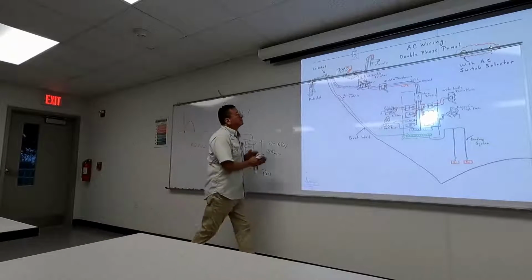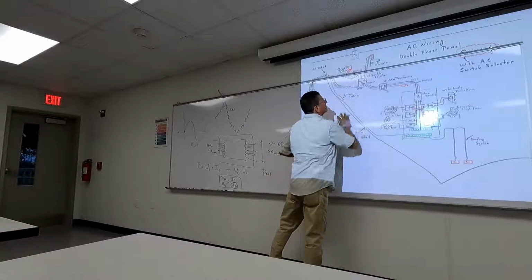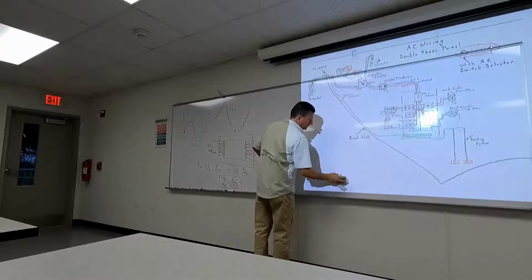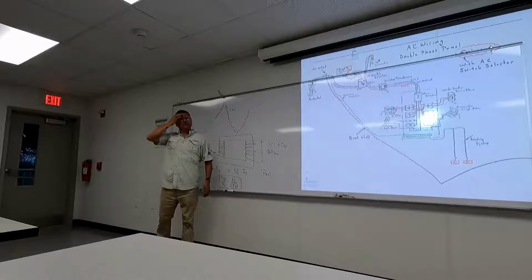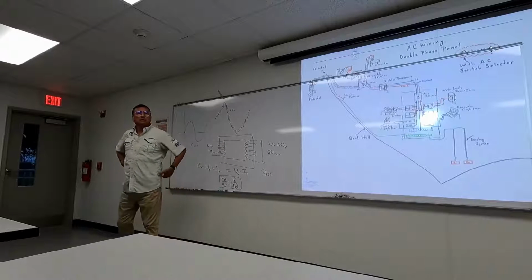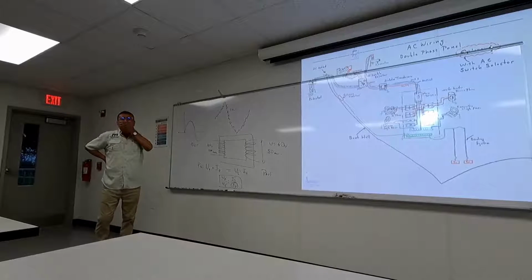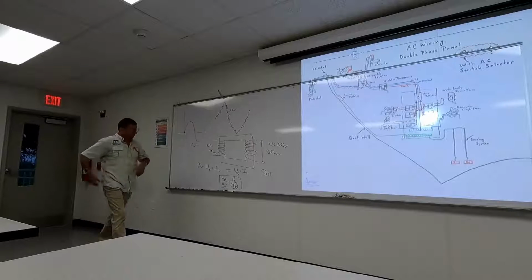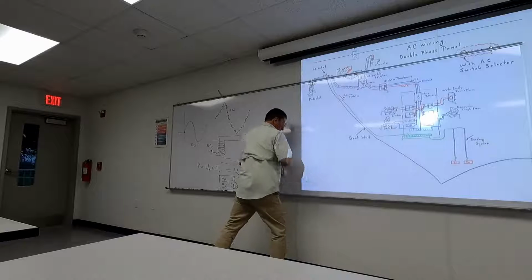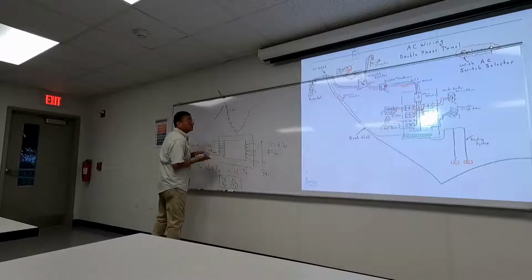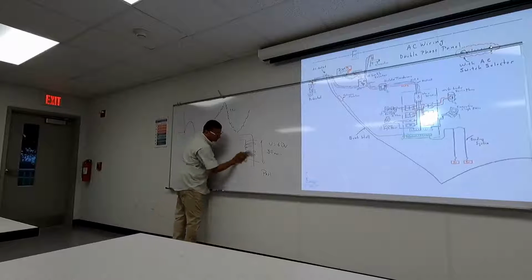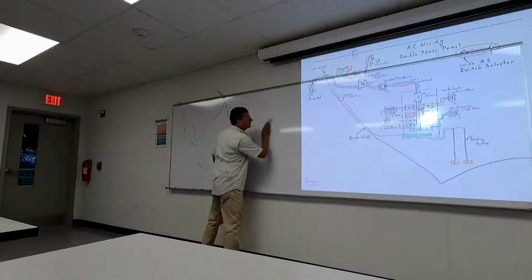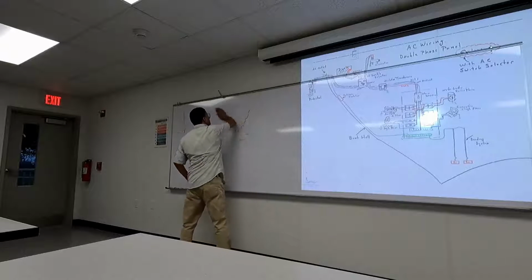Now, if it's all chain, normally that chain will attach to something inside the anchor locker. You can bond that in there. But if it's rope, where you put the chain on the bridle, the slack chain sits on top in a little cradle. It's bolted right there through, and you put a bonding wire underneath the through bolt. Everything has to be bonded. Yeah, the chain.